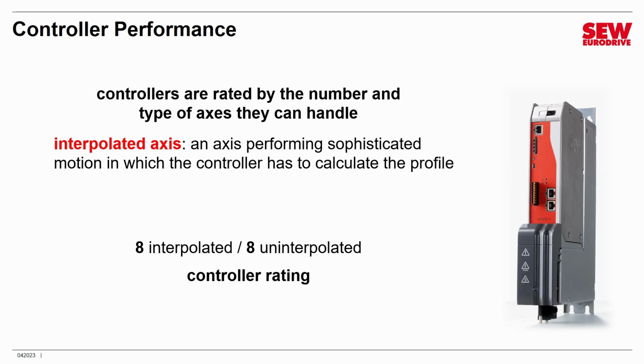Basically, I'm guiding you through this complex motion. And because you're blindfolded, you sort of have to trust me that I'm taking you where you're going. And when we're all done, I say, okay, take off the blindfold, you're there. And wow, you really are. That's what an interpolated axis is. The VFD is just sort of blindly following complicated commands coming from the controller.